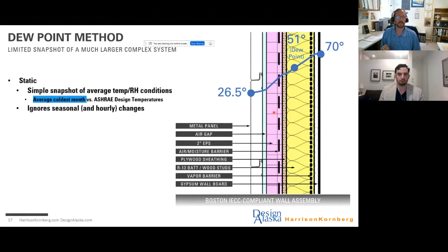And I'm going to specify that this is faced EPS insulation, which is the kind that you get in the box store. It has that polypropylene facing on it, where the manufacturer stamps the brand name and some R value information on it. And we'll come back to that because that's a very important factor. But for now, we're talking about just thermal properties.